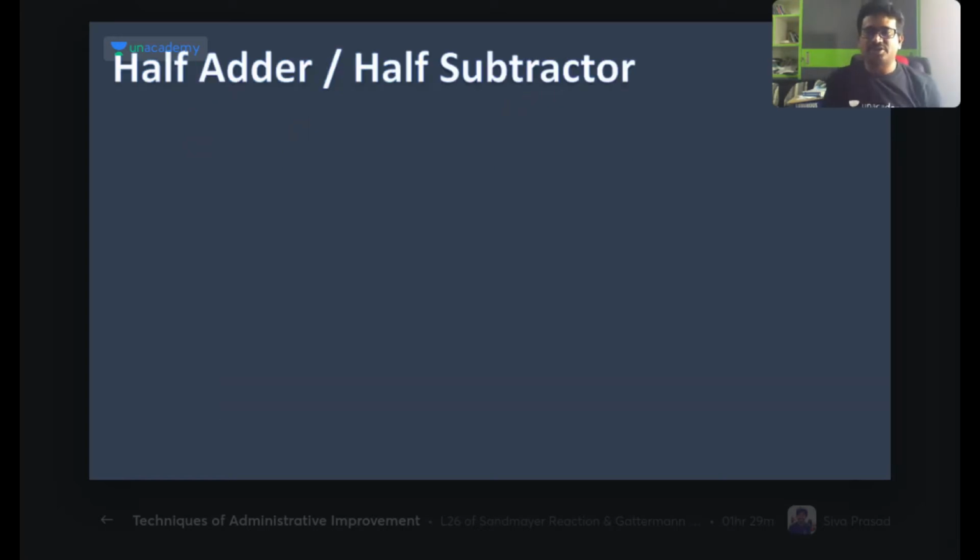Now let us see this half adder and this half subtractor, and how a single circuit can work as both a half adder as well as a half subtractor. For the half adder, we need A XOR B; for the subtractor, the difference is also A XOR B. Here we require AB, and here A bar B. Now let's see how we can implement this.